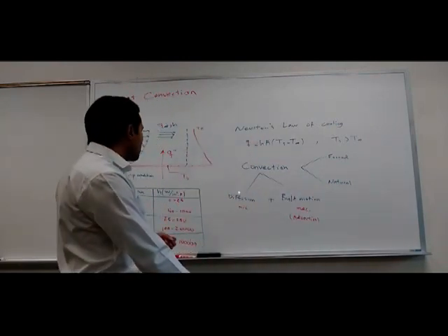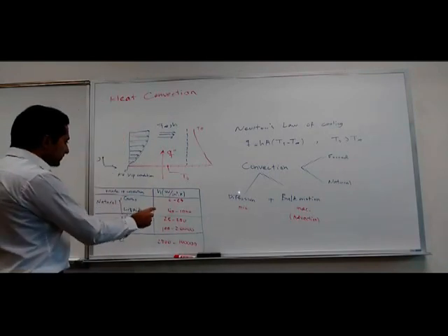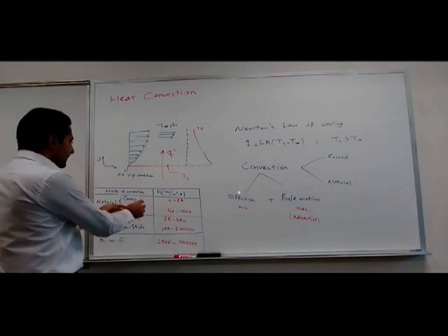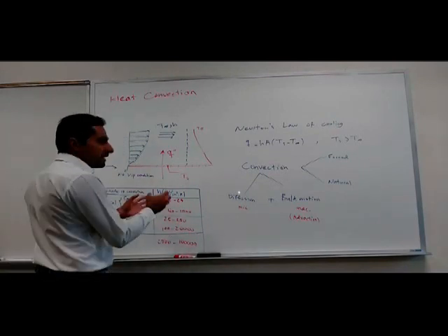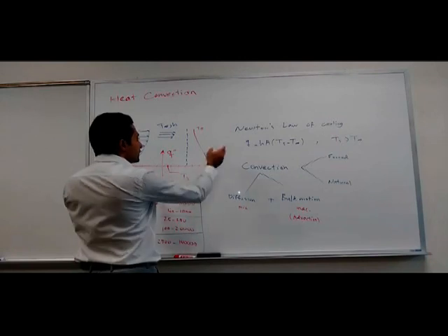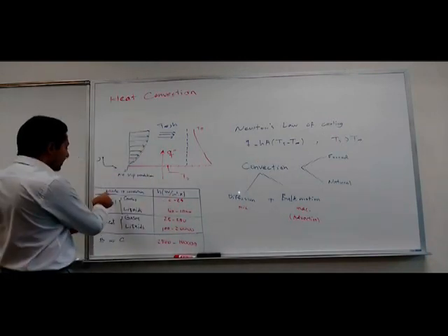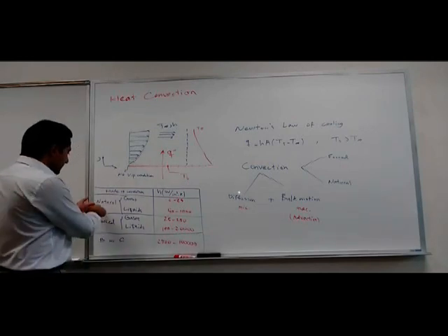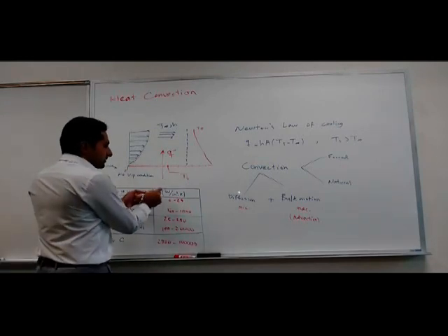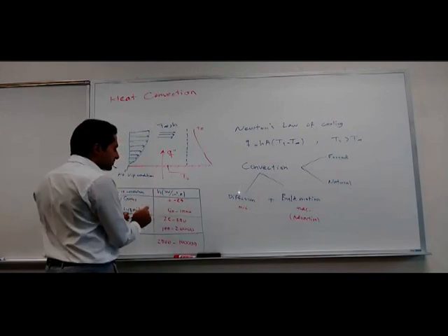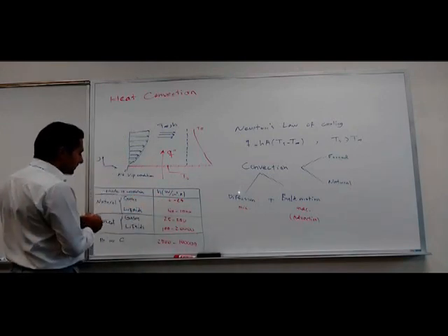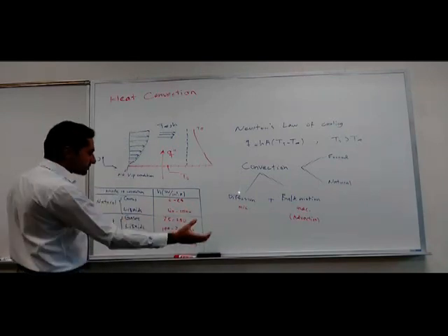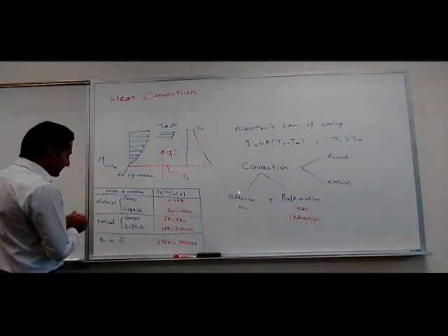The important thing that you need to know here is the behavior or the value range of heat transfer coefficient as a function of the mode of convection. For example, in natural convection, the value range of heat transfer coefficient is narrow for gases and will be greater for liquids.